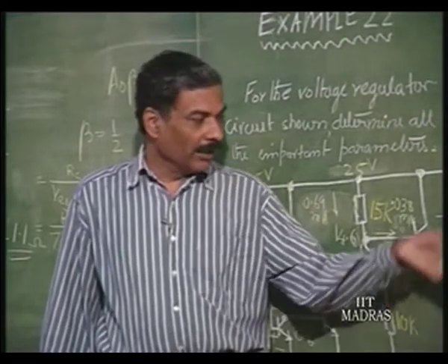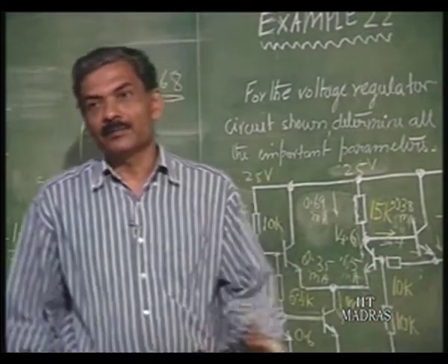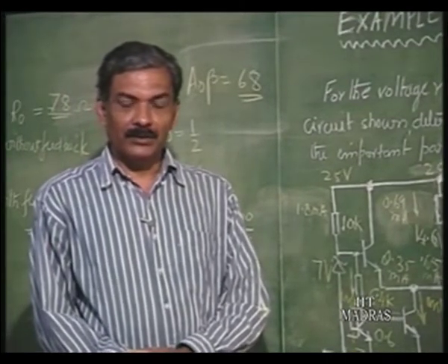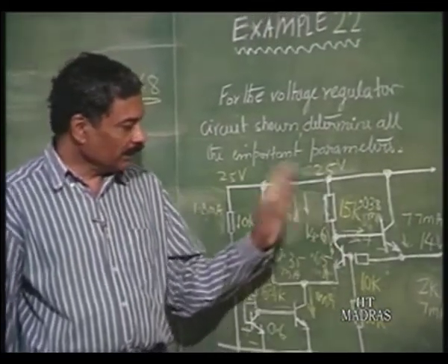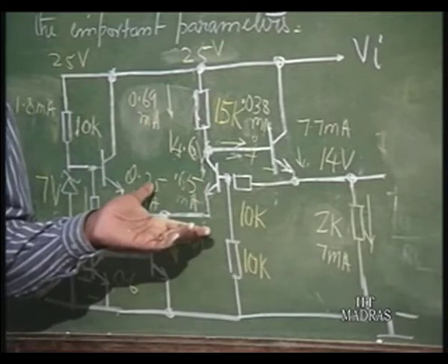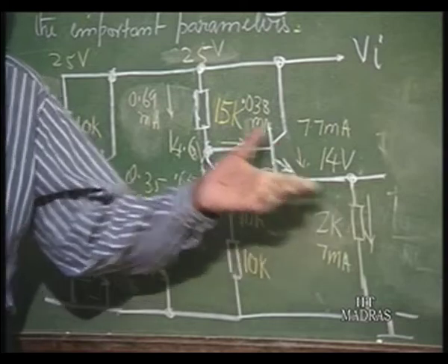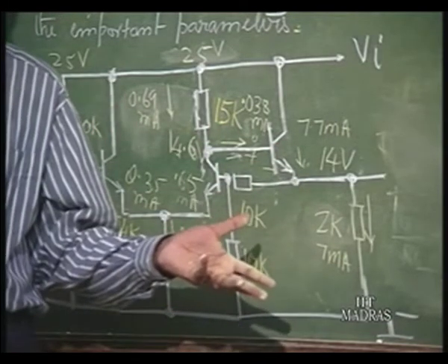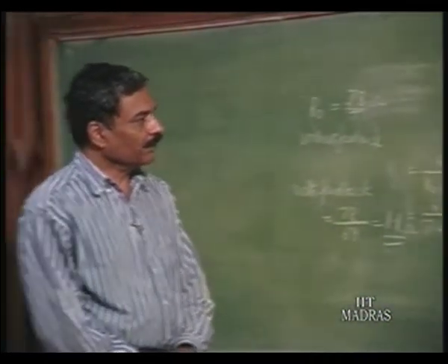So, that output impedance may become pretty high and it may cause problems, unless you purposely reduce it using a special technique. Like now, if it does not use an op amp, the output impedance at low frequency will be almost the same as output impedance at high frequency. The moment you use an op amp, that gets drastically changed. So, output impedance is evaluated.